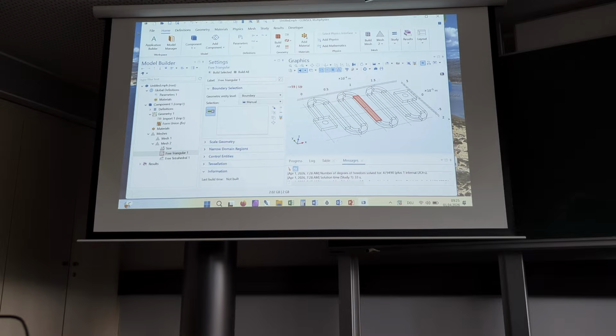That operates on different structures. Now it's its domains, its boundaries. Then I would have to click away a lot of boundaries until I get internal access. You can also change that here from boundaries to domains. You see, now I can select domains, so that is more convenient. And I click the inlet, it's just gone. What is important now, don't forget to disable click and hide. Otherwise, by trying to select,